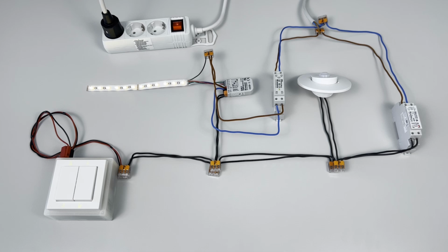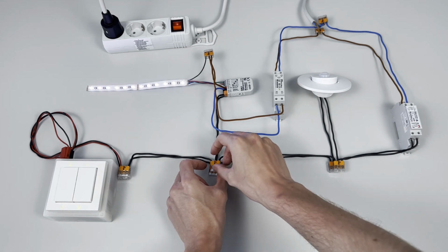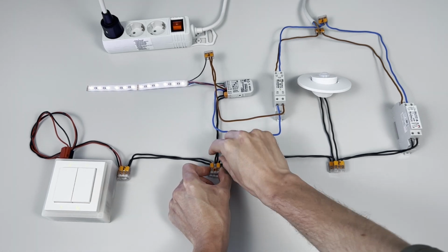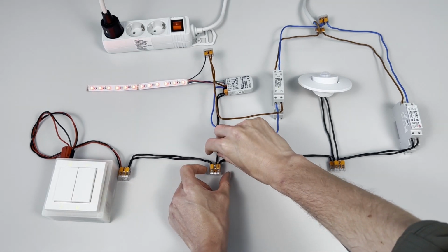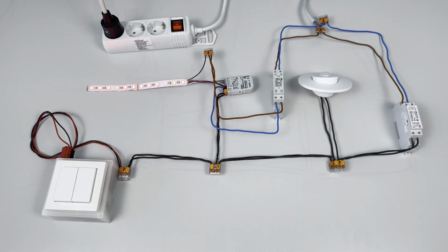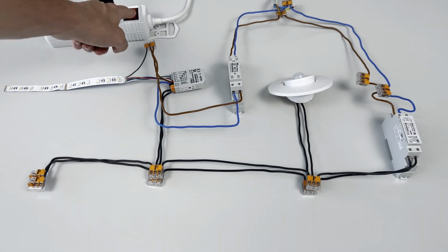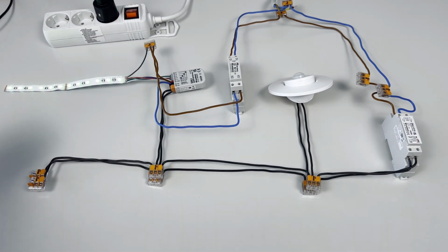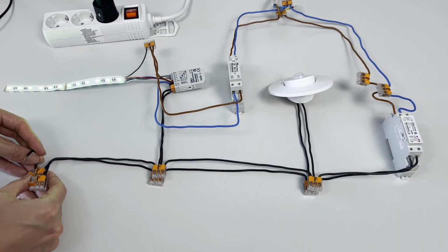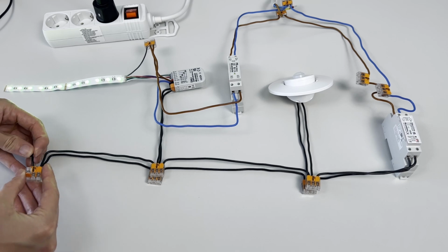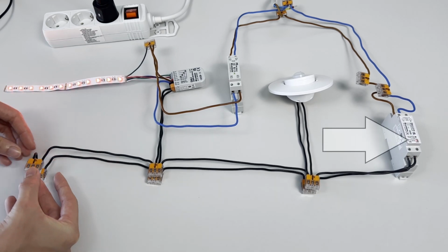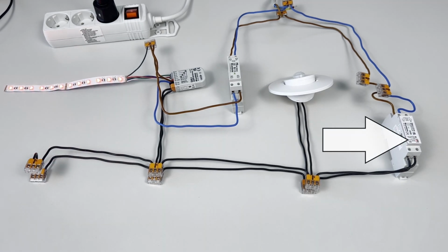If some devices do not react, it may indicate devices are not connected to the DALI line, or there is a faulty device. If a wire becomes disconnected from the DALI line while your system is running, no commands can be transmitted, and the system will stop responding. As a result, dimmers will set their luminaires to their system fail level. A similar behavior occurs in the event of a short circuit on the DALI bus. In this case, dimmers will set their luminaires to the system fail level. If your power supply has an LED, it will begin to flash to indicate that there is a fault.